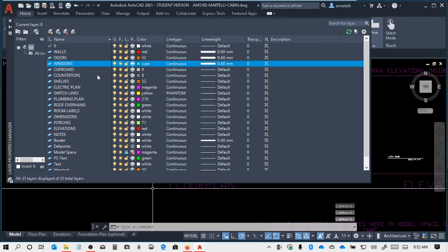Cupboard. Now here's the thing about a cupboard and something about a floor plan I need to describe. A floor plan is the most common and frequent section view of all of architecture. If you were to cut through a house, you would measure from the floor up 40 inches, chop through the walls, and peel back the ceiling, thus revealing the floor. That's what a floor plan is. In fact, it's so common that we don't even call it a section view. It's simply called a floor plan. Cupboards are above that 40 inches.